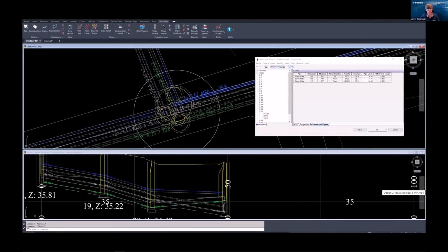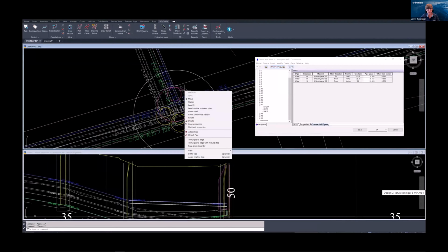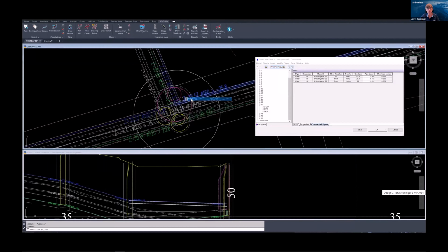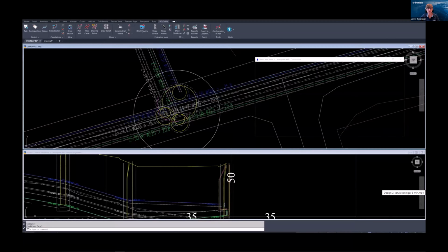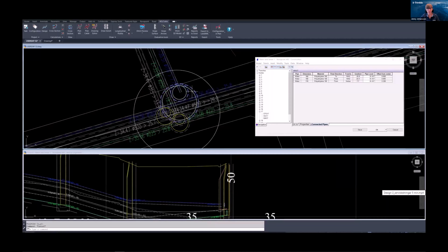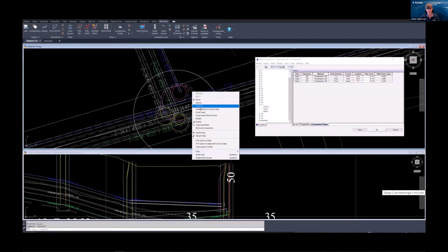In the same way, I am now going to move the connection for the water. Select move, and after moving it, we will point out a new place. And then we have to right-click it and snap the pipes to center of the manhole.